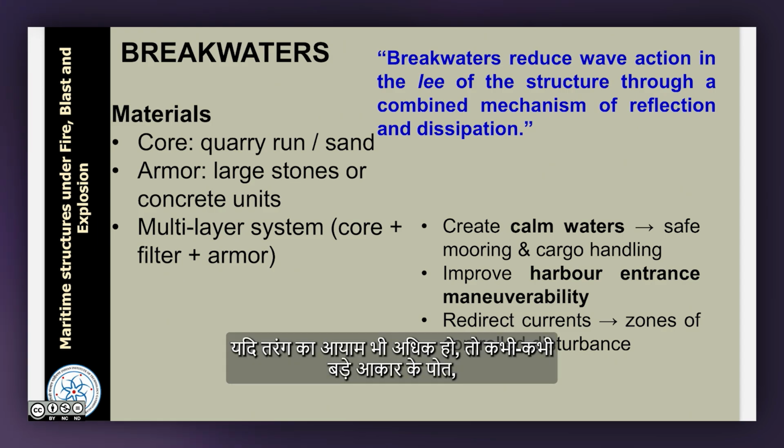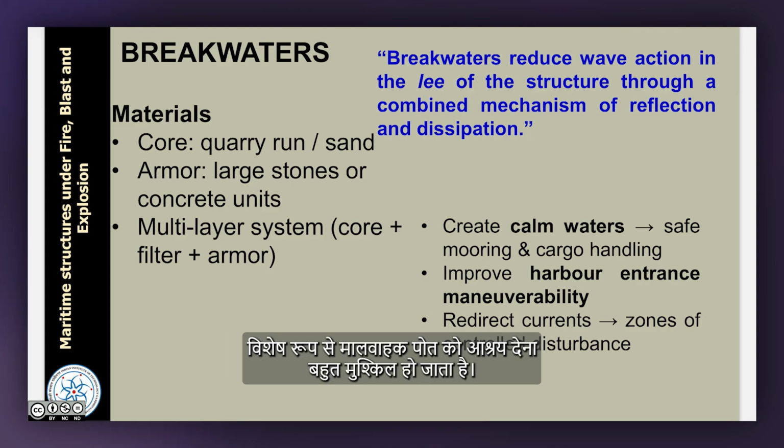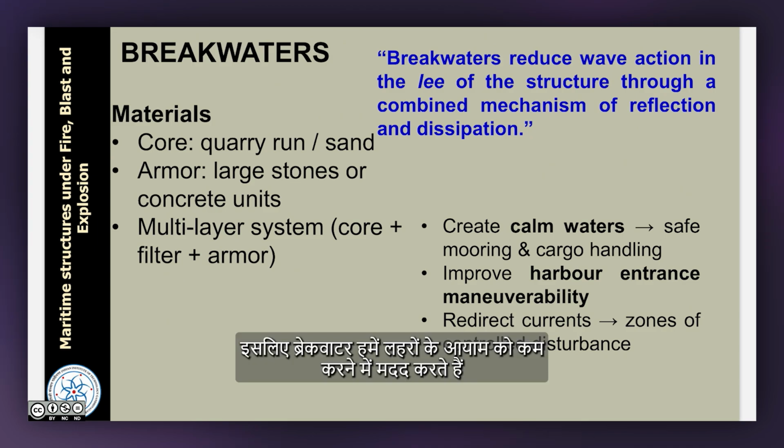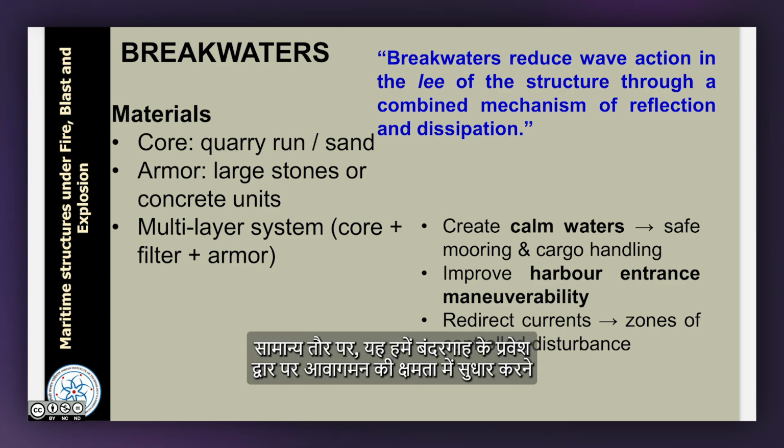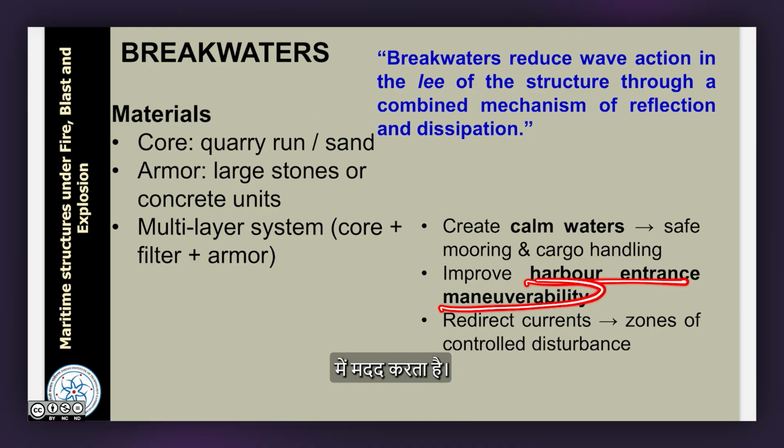If the wave amplitude is larger, sometimes it becomes very difficult to harbor a vessel of a large size, a cargo vessel essentially. So, breakwaters help us to reduce the wave amplitudes as the waves reach the coast side or the harbor side. In general, it helps us improve harbor entrance maneuverability.